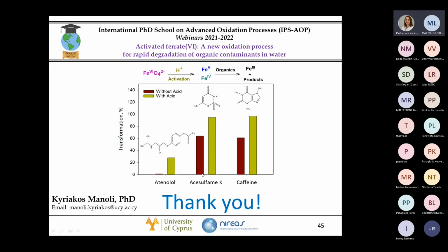The biggest challenge of the Ferrate(VI) technologies is the stability. Ferrate is not stable, it's stable only for a few hours. So it cannot be used like chlorine, for example, that we can have a barrel and it can stay there for months. Ferrate is not stable, so either we should go with the solid Ferrate(VI) powder, which has other implications in producing powder Fe(VI) instead of liquid Fe(VI).